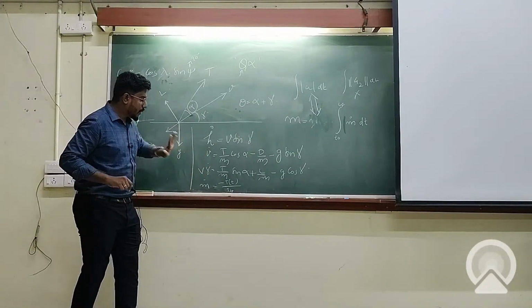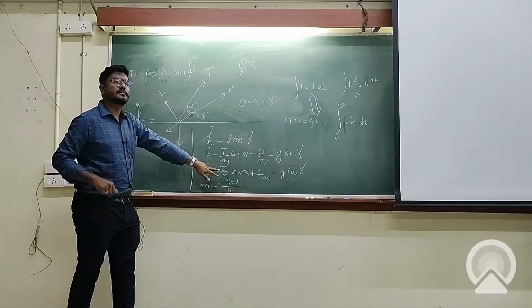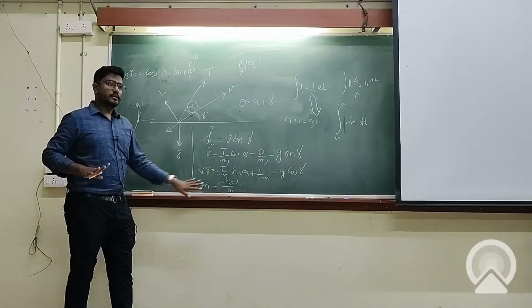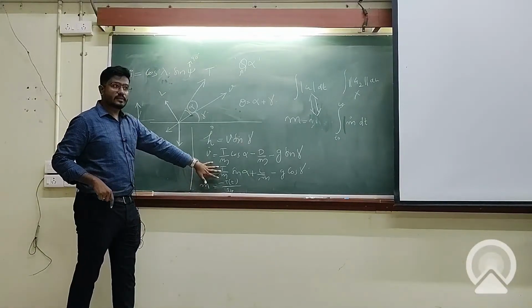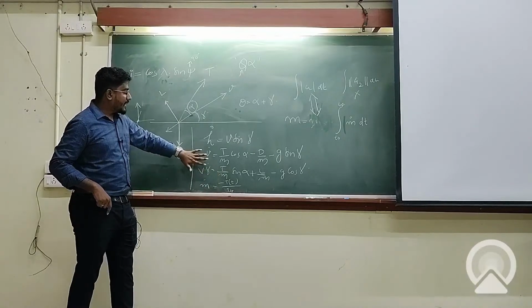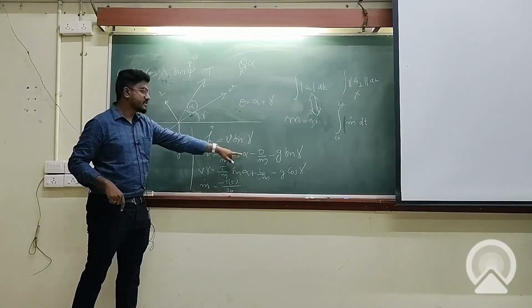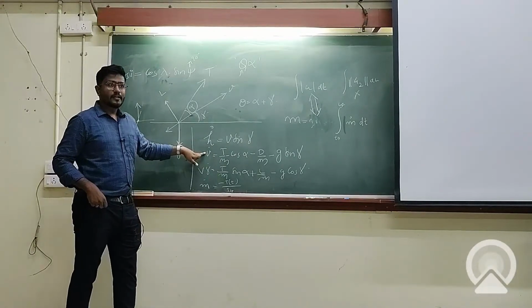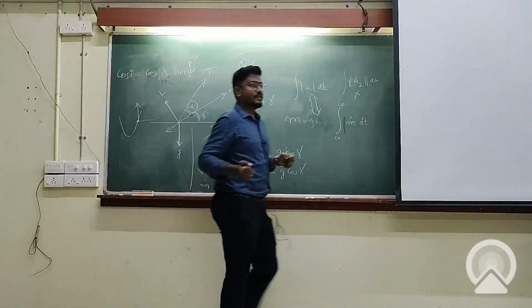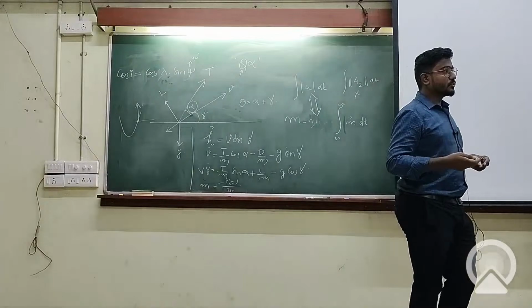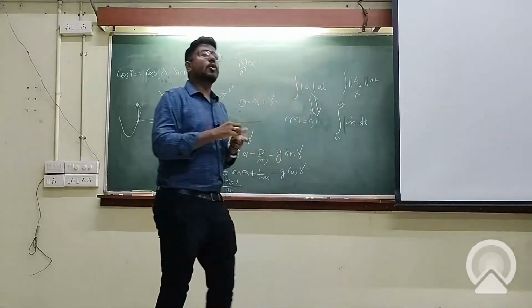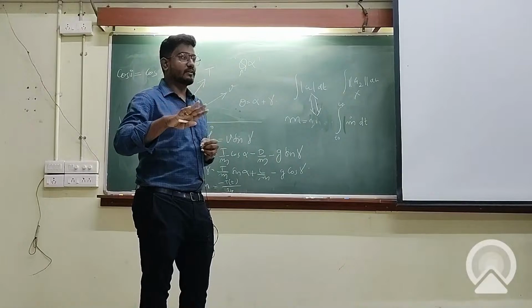That means the point to be noted is that thrust doesn't have a role in rotating the velocity. In gamma dot, the thrust term does not count. And since cos alpha is 1, thrust is completely aligned along the velocity. Isn't that optimal? That is the optimal thing to do. Gravity is actually taking the job of rotating the velocity.